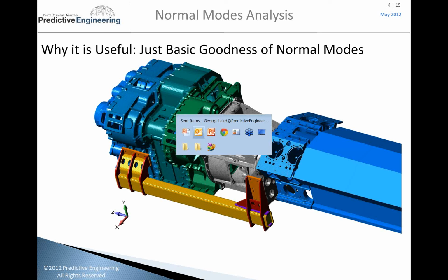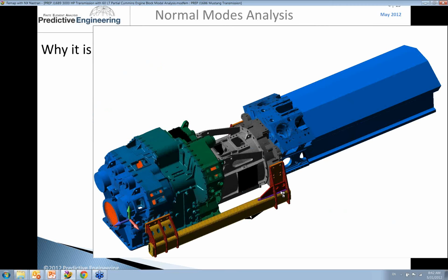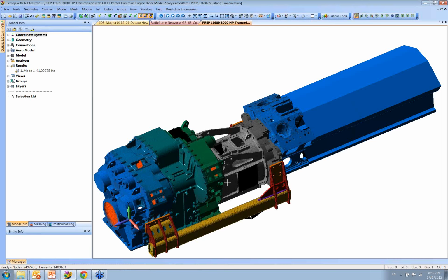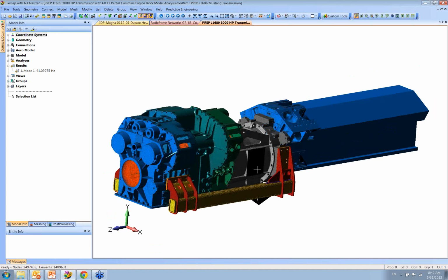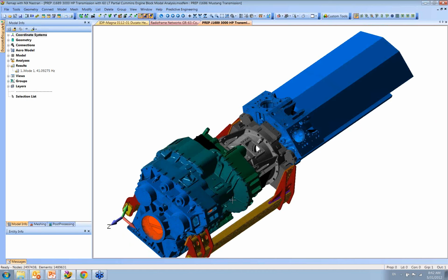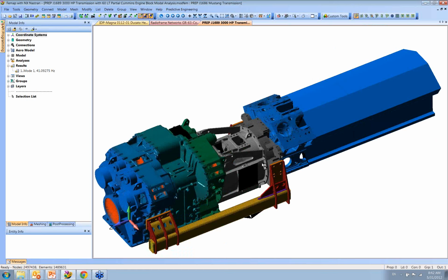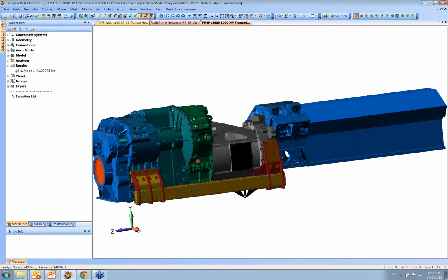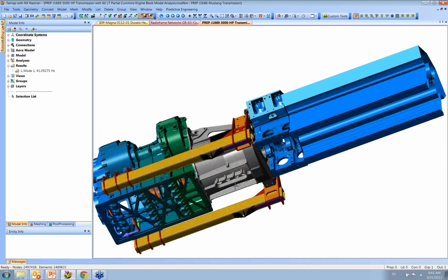This is one of the things in FEMAP: when you're doing these web meetings, the computer in the background is processing, actually compressing video and sending it out. So when FEMAP is trying to move stuff in models, it can be difficult. This model is 2.5 million nodes, and it moves a lot faster when it's not in video mode. It has all the castings, tetrahedral mesh, plate elements, rigid links, and a partial engine block. It was quite massive.